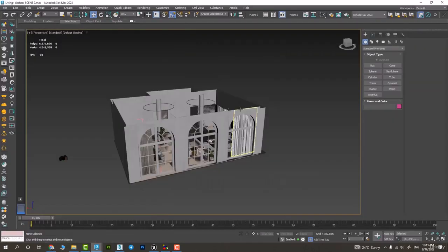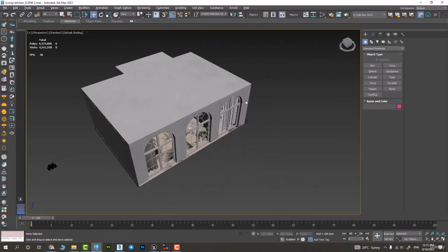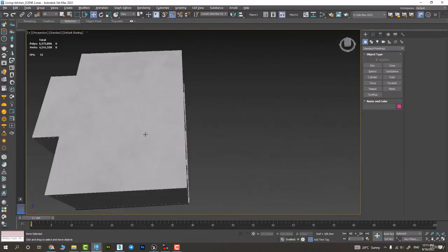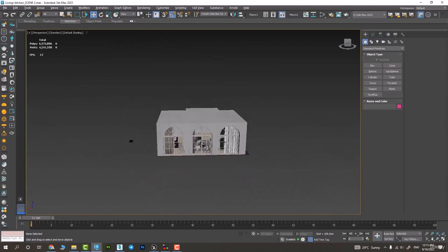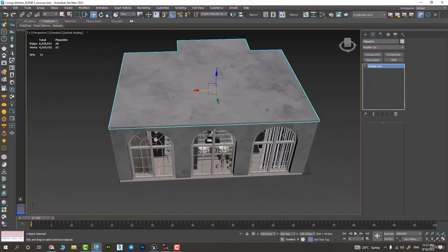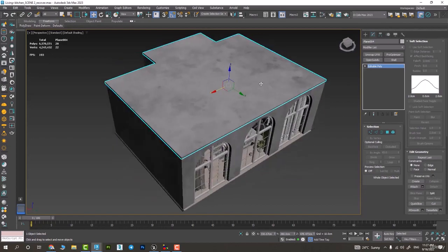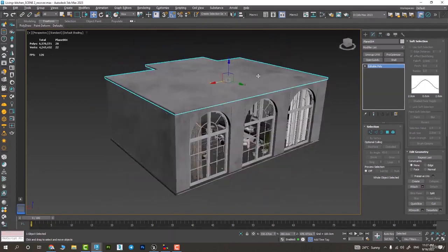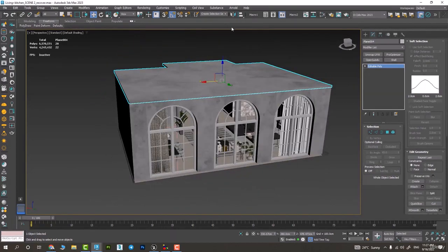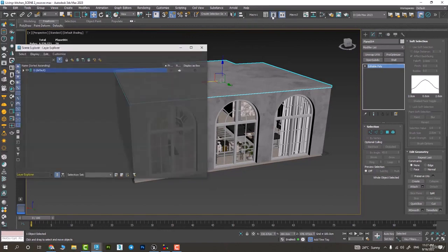Now, how do we use the Datasmith plugin to import this scene, this building, from 3ds Max into Unreal Engine? Okay, like I said, the first thing that we do is to divide our project into different layers. And we can use this button, Toggle Layer Explorer, here.